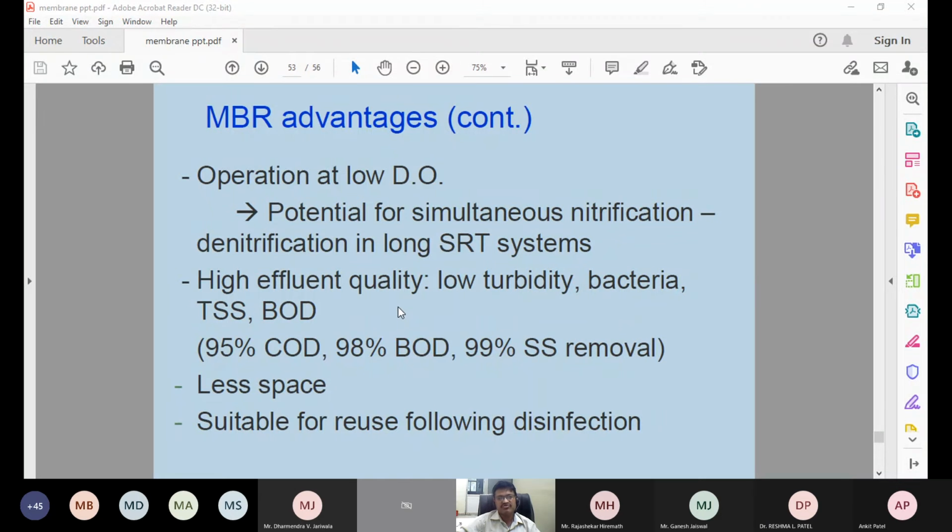Then you have to drink it. So up to 1500 they are allowing it. But if it is more than 600 or 700, one problem is taste, and in the long term, I don't know how much research there is, but if you take high TDS water, it may not be suitable for health. Therefore, if TDS is more than 500 or 600, we can use the RO system.